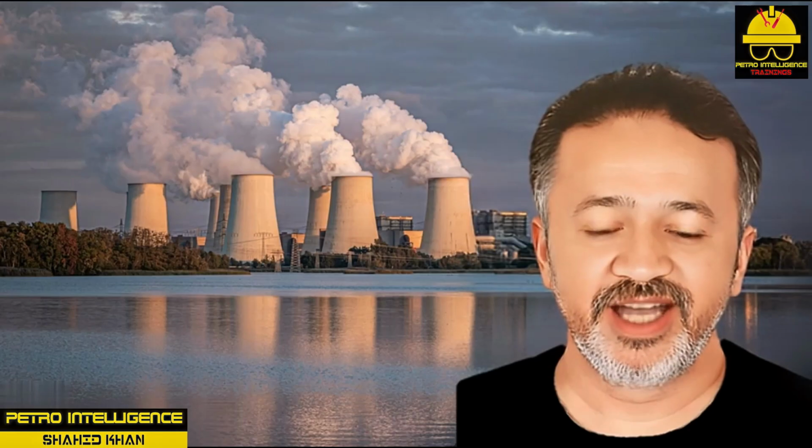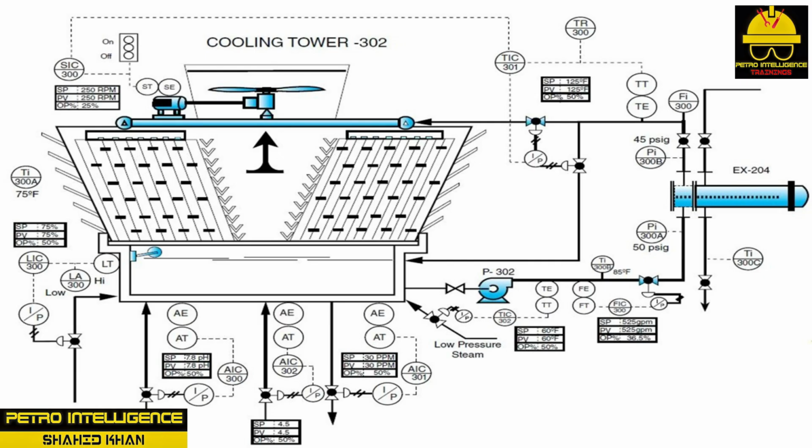Blowdown and cycles of concentration problems. Concentration cycles in cooling towers range from 3 to 7 and are dependent upon the quality of the makeup water. Circulating water in CTW302 is filtered and treated with biocides and algicides to prevent microorganism growth, and a control system for pH adjustment.